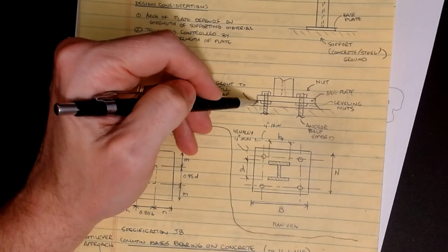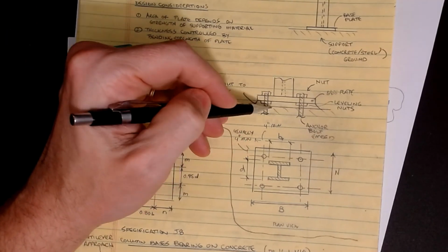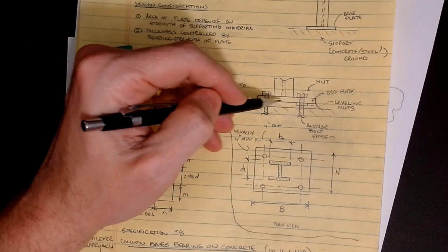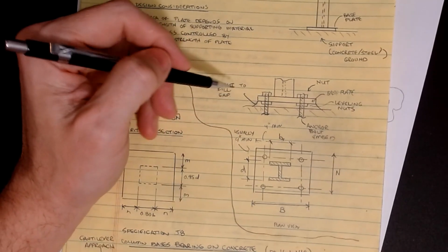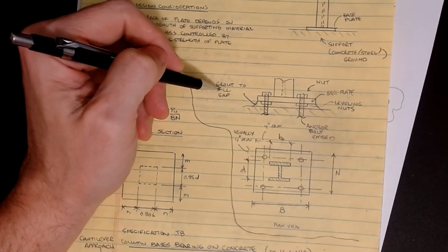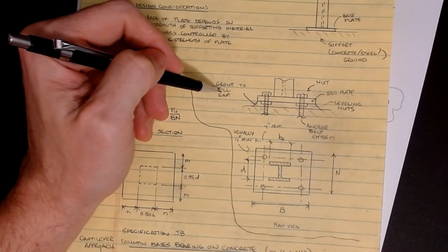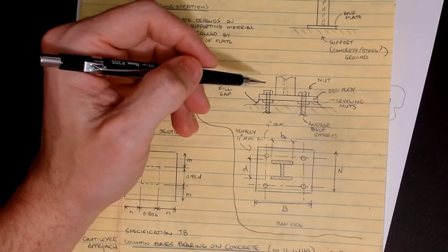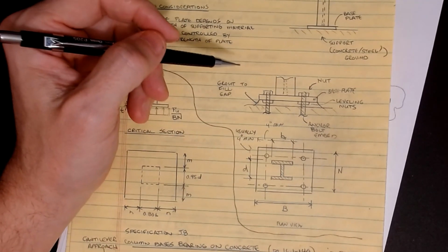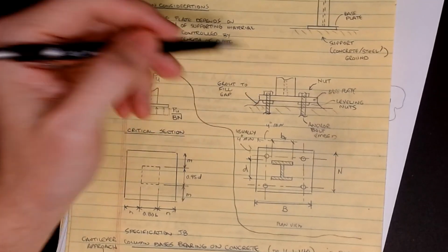So getting this grout layer installed correctly, without holes or any pores or air pockets, is a very critical issue. Okay, normally this is a very soupy material, very liquid, not quite a liquid, but it's liquid enough that it free flows, that it will flow and fill those holes very easily. But that's kind of the leveling mechanism that we're looking at.